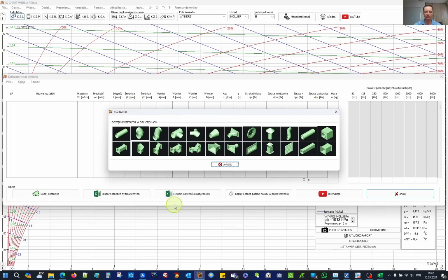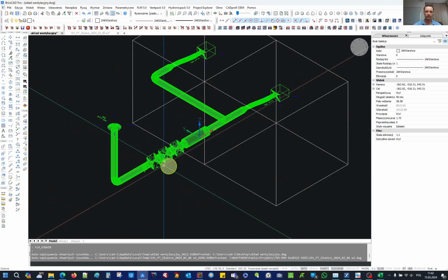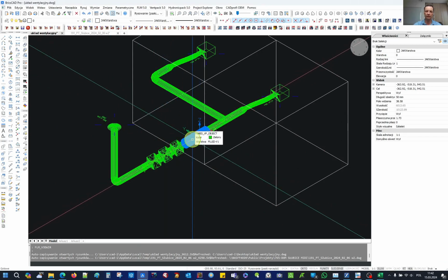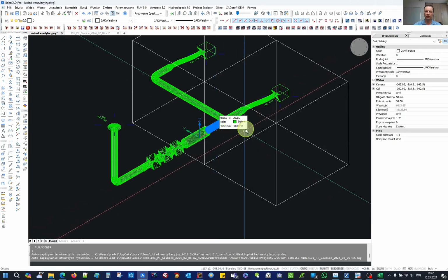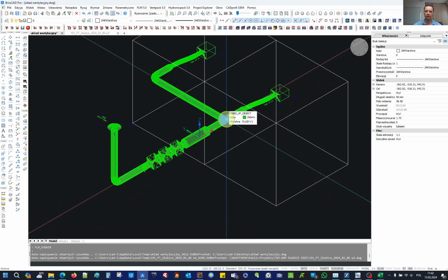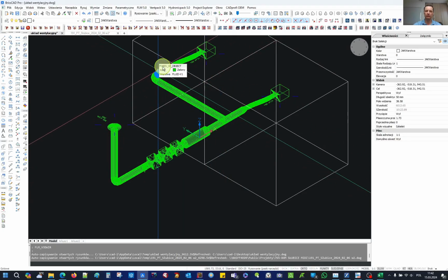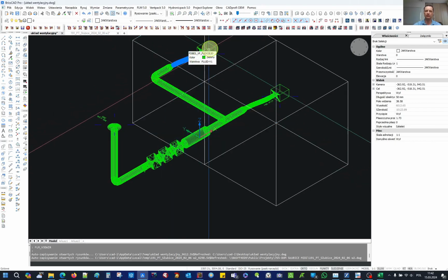Alright, so let's perhaps start with beginning the calculations. I'll take another look at the drawing. So we start from our source, which is the fan. Then there will be the silencer, followed by a section of the straight duct with a length of 1 meter. Then we will have an equal diameter T. We will have here a section of duct with a length of 4 meters, 1 meter section, reduction, flexible transition, and the air vent blowing into the room.